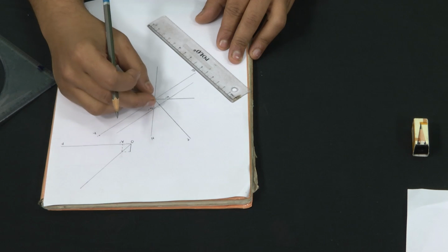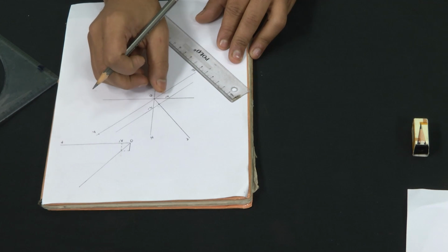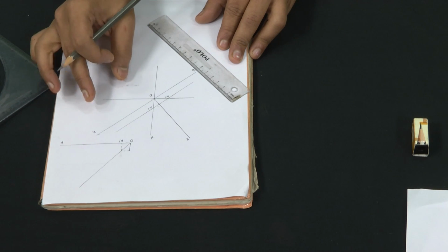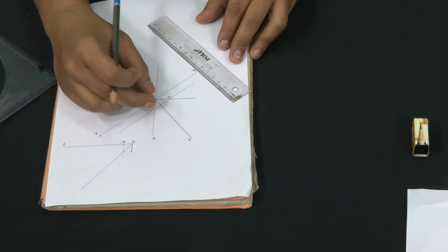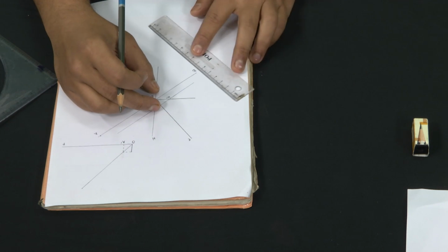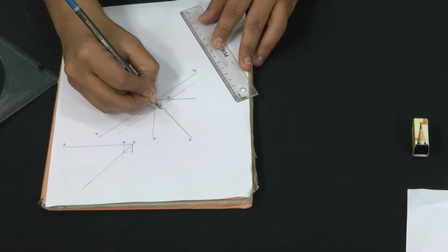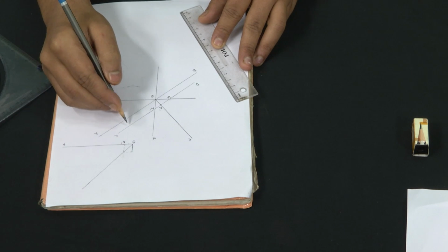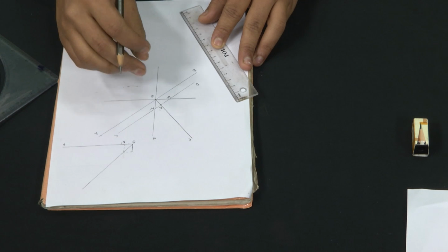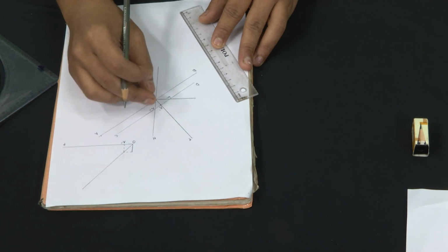So, O N dash will be any lineation that is trending towards north, and O W dash will be any lineation that is trending towards west. Now, O N dash is the plane separation of that lineation, and we know that the distance is 100 meters originally, because this line, if I represent it as CD, CD is the 100 meter strike line. So, now in order to find out the plunge of lineation that is trending north and contained in this bed,